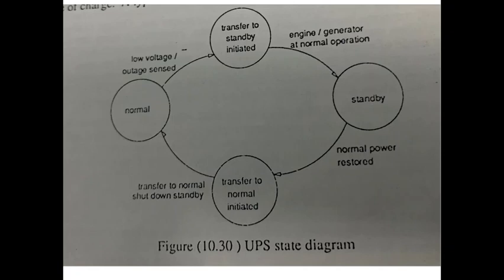All rotating UPS require a transfer switch whose function is to transfer the load from the main supply bus to the standby source. The transfer switch must carry full load and it must be overrated in order to allow transfer of inductive loads. The transfer switch must be mechanical.